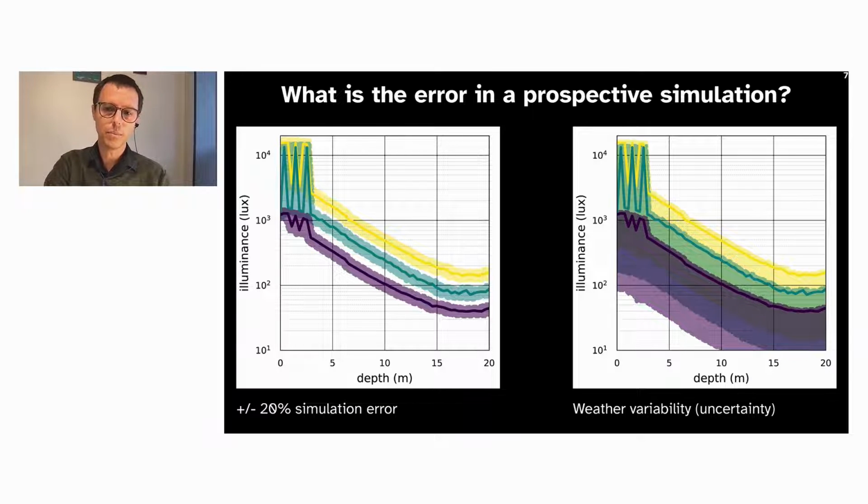What can we possibly gain from a 10% improvement in simulation accuracy if we can't estimate anything within a factor of 10 anyways? Should we just use this to justify falling back to simpler heuristics? Can we even say anything useful about the difference between blinds and shades? Some component of the simulation error will have to be taken as true uncertainty, but the rest, as well as the range of possible weather conditions or dirt on the windows or any other changes, has high covariance across the comparisons. In other words, weather uncertainty, as long as we have a representative set of sky conditions, will not flip the order of the results. Each option will move in tandem across the error band.